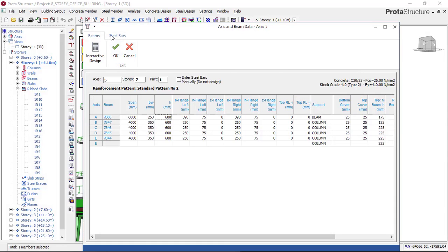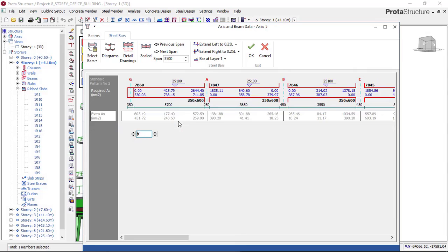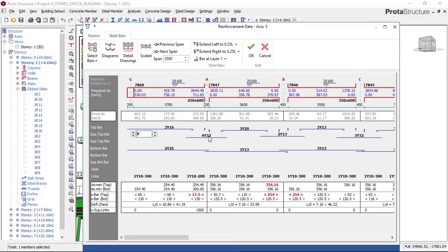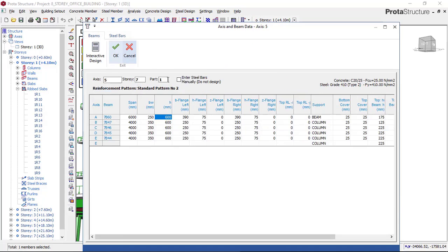So now you can see that if I come here on this beam, this is failing, this is showing 32, and if I try to decrease to diameter 25, I'll be failing here. So I'm going to increase my depth of beam to 750 or 650, but I don't want to waste my time changing beams and depth of beam every time. So let me just choose the beam, because from experience I already know that what will be able to withstand the load on that beam is 750.